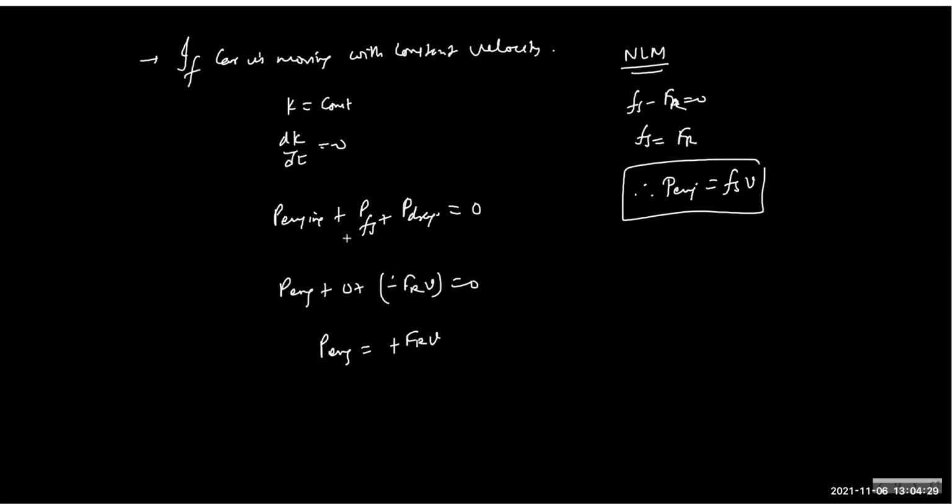Definitely high RPM will give you lesser torque, so your vehicle will not move very fast. So you need to put it into low gear to create the torque. Now the wheel is set into motion, omega is already achieved, so we increase the gear to decrease the torque, increase the RPM, and so on. This is how you match the speed with gear.